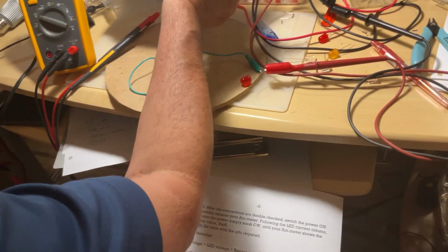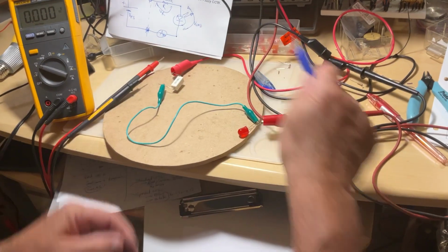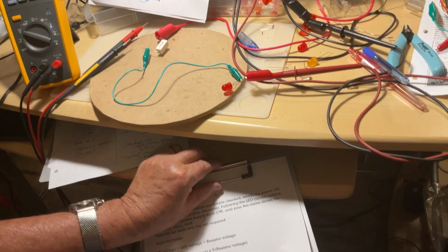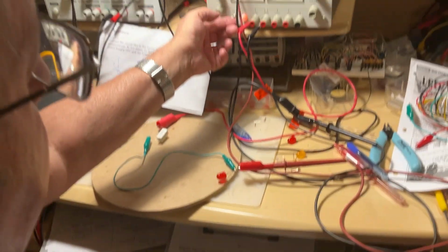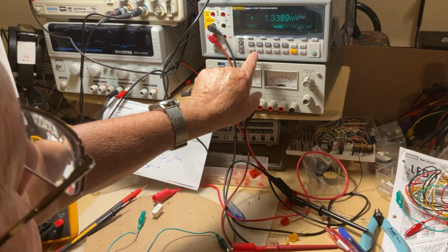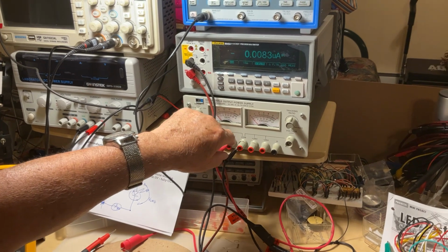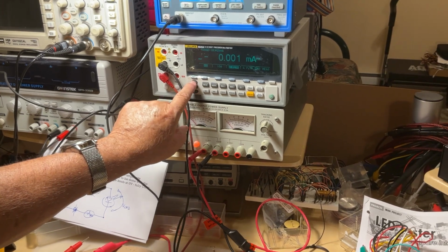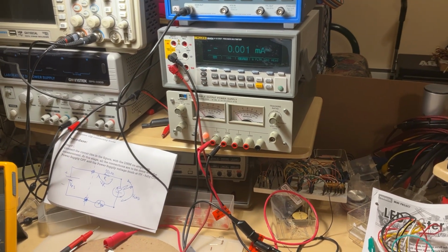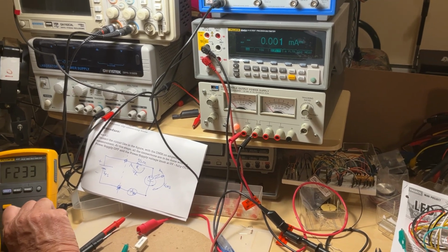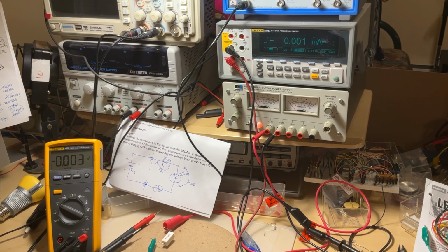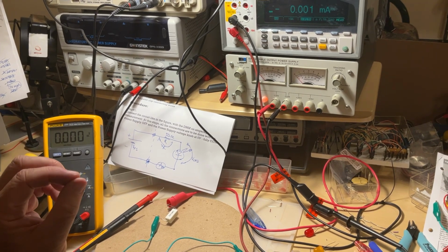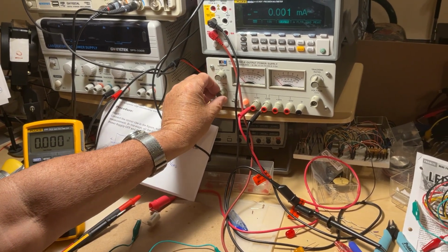We have the diagram here. And now we try to fill the table with measurements. The power supply goes on. The meter goes on. We want the meter to measure DC on the range of 400 milliamps. And with the other meter, we're going to measure voltages. Okay? So now, what we're focusing on, we just very gently turn the knob clockwise of the power supply